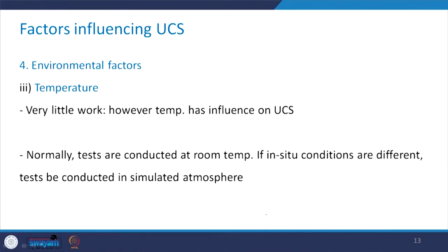Now, regarding the effect of temperature, although very little work has been done, whatever work has been done shows that temperature has a significant influence on UCS. Normally the tests are conducted at room temperature, but if the in situ conditions are different, then tests should be conducted in a simulated atmosphere.